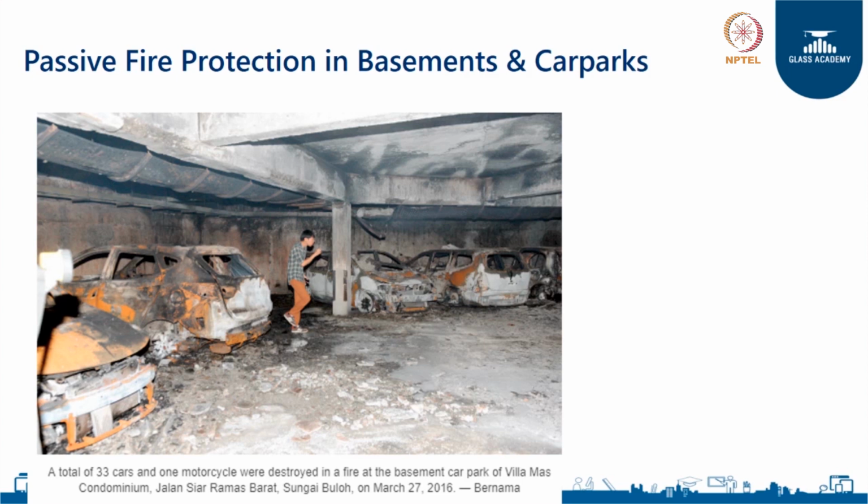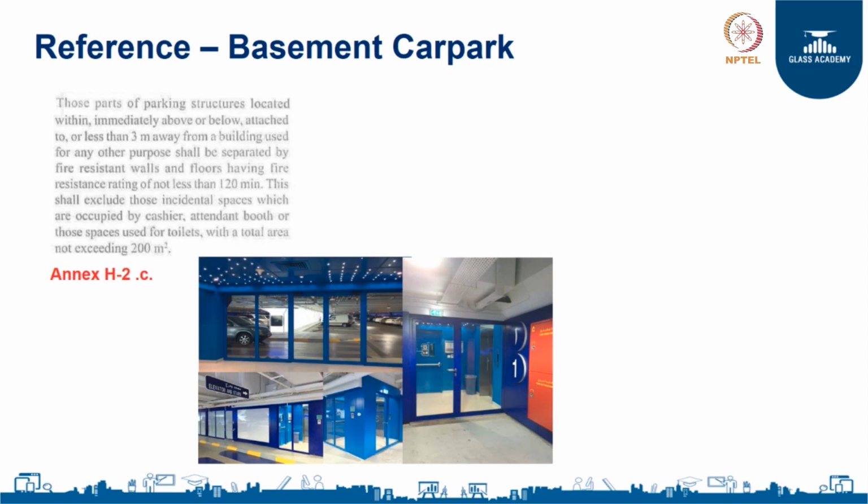If you look at it, every basement will open up to a lift lobby, like you see in this image, in this slide here. This is the entry from a basement into an elevator or lift lobby. Again, as in the same example, if we do not enclose a lift lobby, there is a possibility that the whole building itself can be on fire. As a result, it is of much importance to make sure that the lift lobby of any building, be it basement, upper floors, or a car park, needs to be enclosed. It needs to be enclosed for a duration of 120 minutes as per Annex H2C.